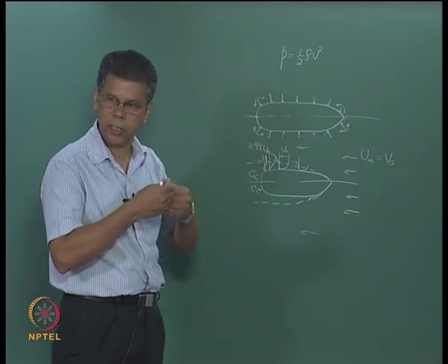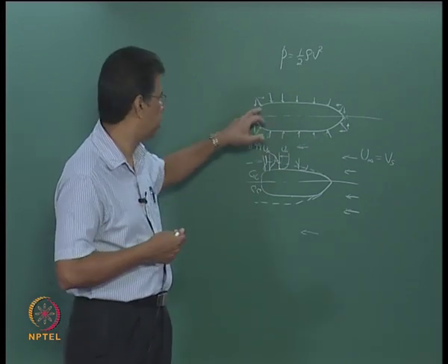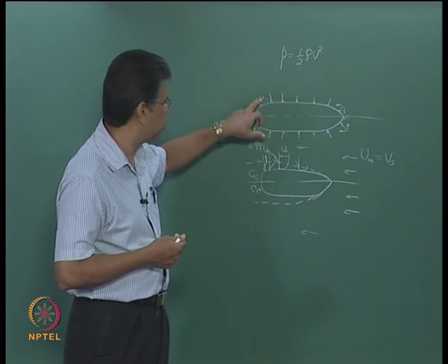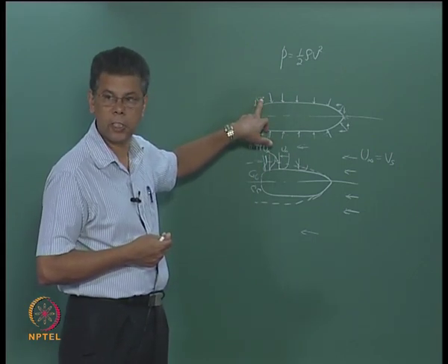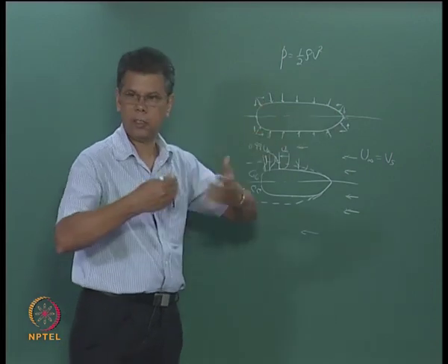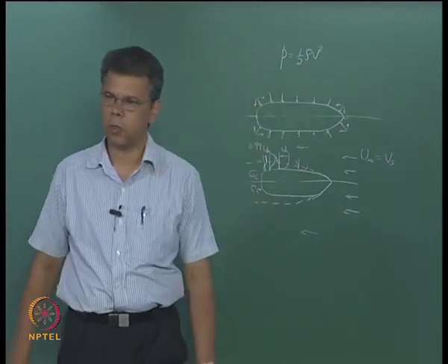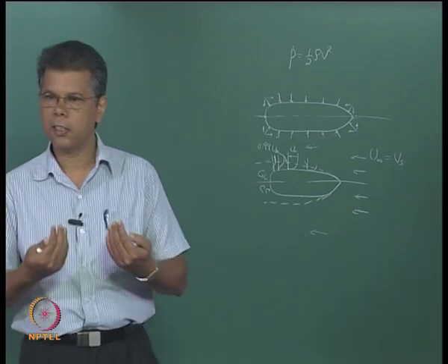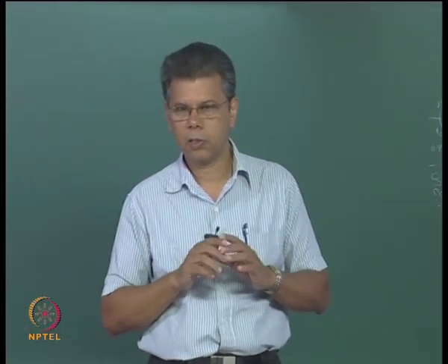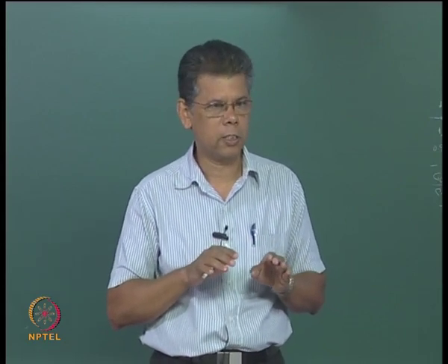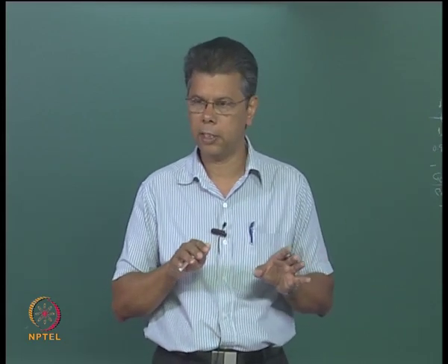So when the velocity is there, the pressure drops. When the pressure drops, what happens to this component? This component reduces. So effectively the opposing component is more dominant, it will increase the opposing force, and the resistance increases. So you clearly understand what is viscous pressure drag or pressure resistance.